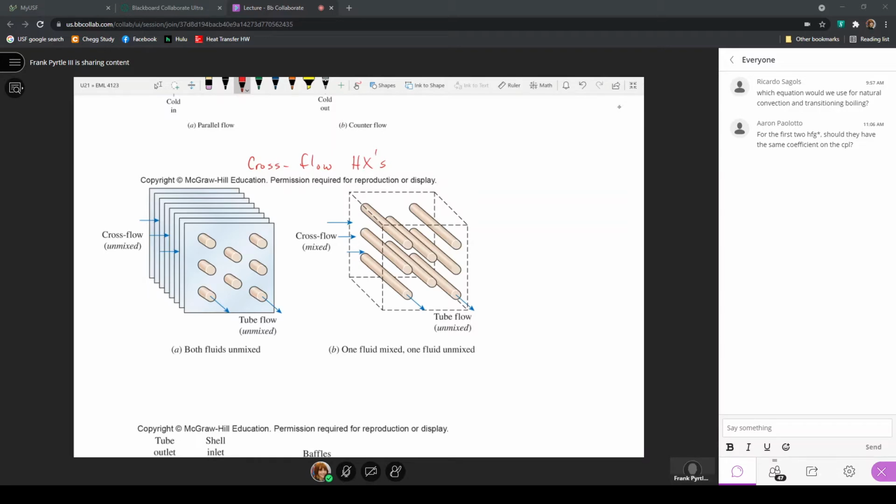But in this configuration, you can have fins. So in a radiator in your car, the engine coolant moves through the tubes, there are fins, and the air moves on the outside. Now, the reason that fins are used is because if there are no fins, like in this configuration here, the heat transfer only occurs from the outside. If the hot fluid is moving through the tube, heat transfer only occurs from the outside surfaces of these cylinders into the air that will be moving around it.